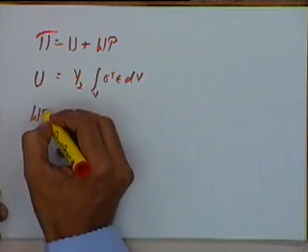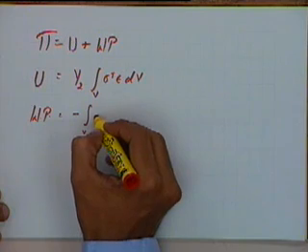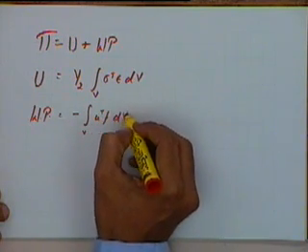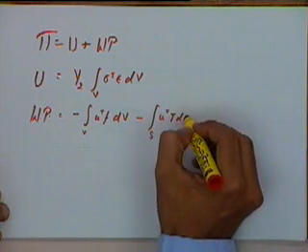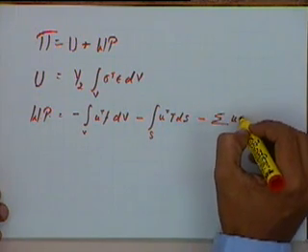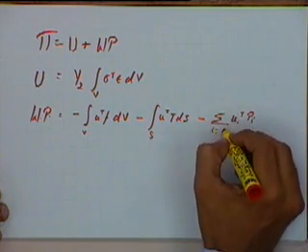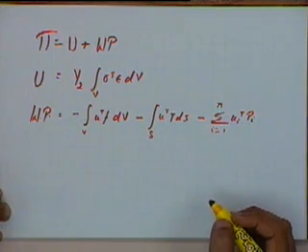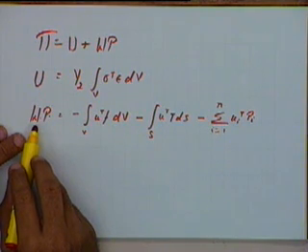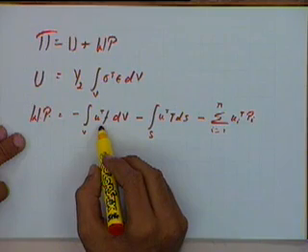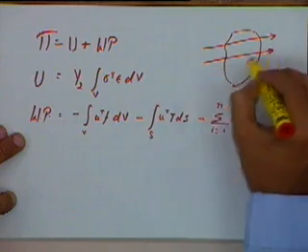And the work potential would be minus the integral of U transpose F dV, minus the surface integral of U transpose T dS, minus the sum of all Ui transpose Pi, with i going from 1 to n. This work potential is essentially the work that would be done against the forces that are acting. So if there is, let us say, a body force, this is my object and there is a force field here like this.